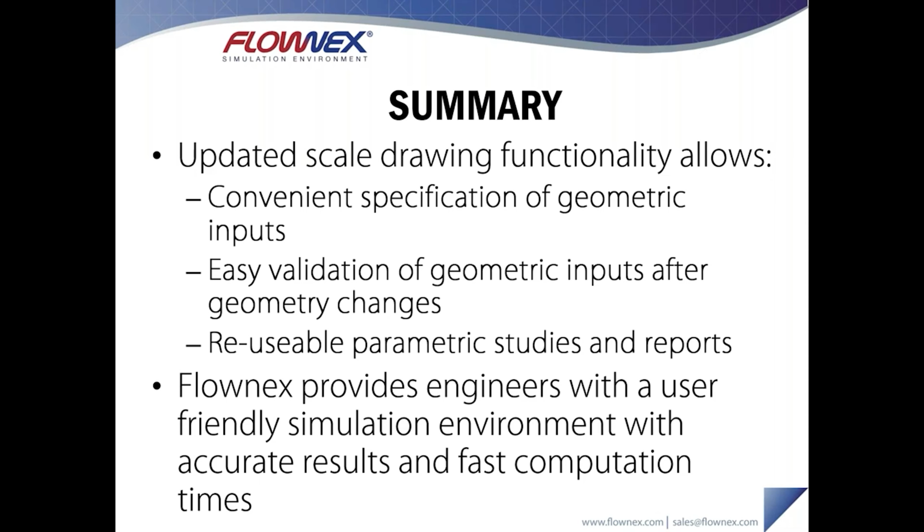Lastly, it also makes it possible for us to reuse our parametric studies. So in the first iteration, I set up a parametric study and was able to reuse the same parametric study in the second iteration. Often, if you have quite a large change in the geometry of your system, it might almost be more convenient to insert the components again from scratch to ensure that you don't forget to change an input. By linking the inputs directly to geometry, you can be confident that all the inputs will be changed, and then you can safely reuse models.